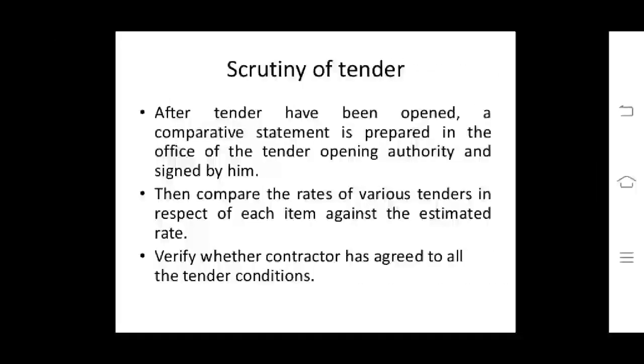Scrutiny of tender. After tenders have been opened, a comparative statement is prepared in the office of the tender opening authority and signed by him. Then compare the rates of various tenders in respect of each item against the estimated rate. Verify whether the contractor has agreed to all the tender conditions.